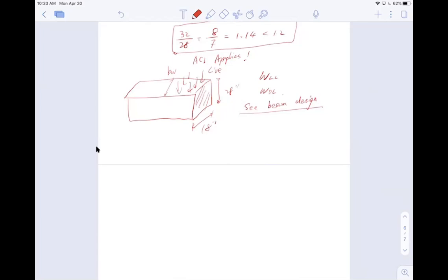If we forgot how we do beam, you can always go back to see the previous lecture notes. So be careful. Yes, indeed, in the exam, I'll be looking for the unit there. For the slab, it's always a distributed load. After you calculate everything in the factored form, it should be pound per foot squared. For beam, it's going to be pound per foot. And in terms of moment, for the beam it's just pound-foot or kip-foot, and for one-way slab it's going to be kip-foot per foot.